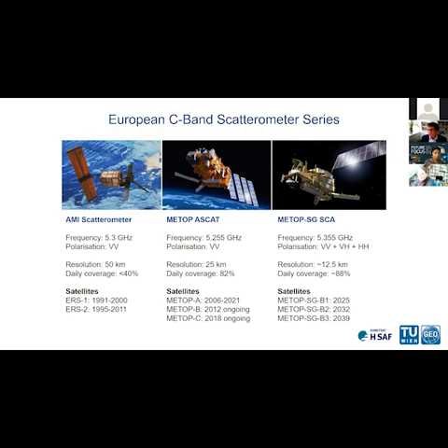This, over land, is extremely important information because, for example, we know that for grassland areas, the HH signal will be even more sensitive to the soil moisture content compared to the VV. And we know that VH is going to be more sensitive to things like vegetation and other volume scattering mechanisms. So there is a lot of additional information in those data.